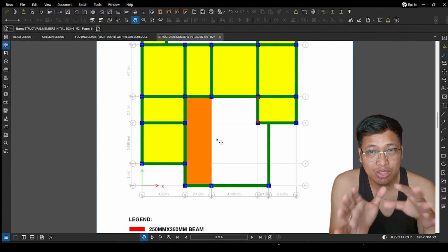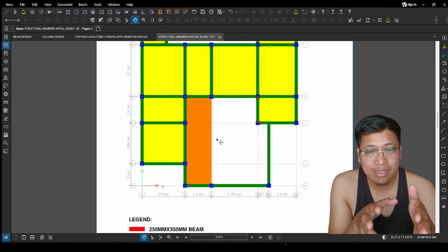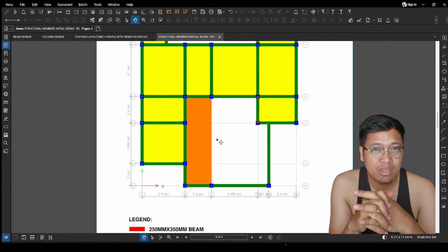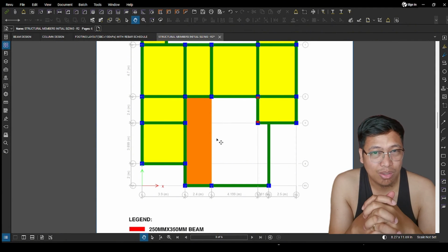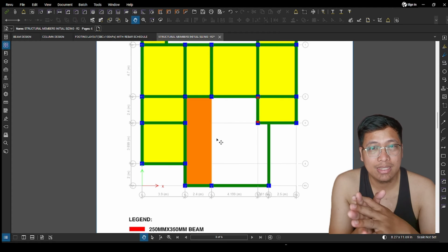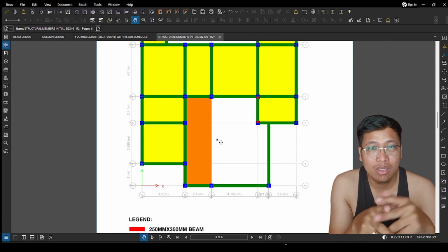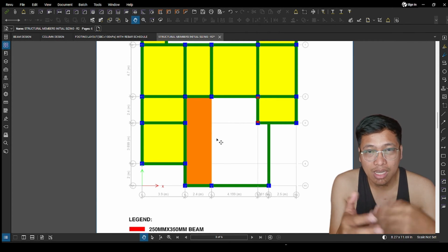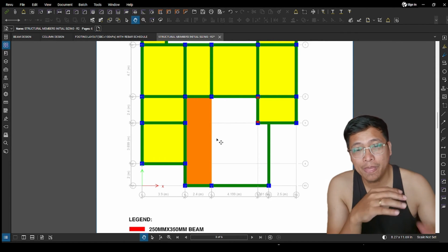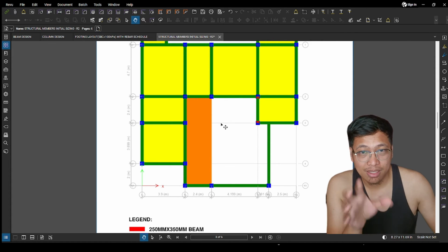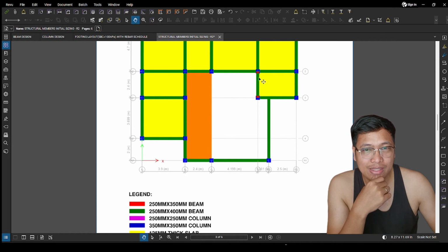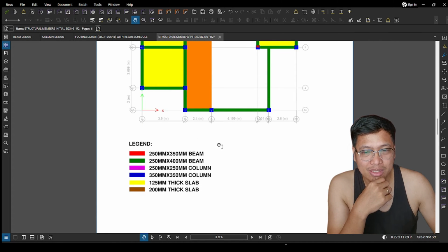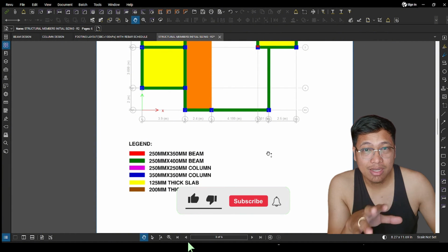So in that particular side, if we produce a beam there, the requirement will be deeper because the span is long. That's why we prepared thicker slabs instead of introducing beams and columns. Initially, there was a column there, because there's a stair here. So, we just propose a thicker slab here.